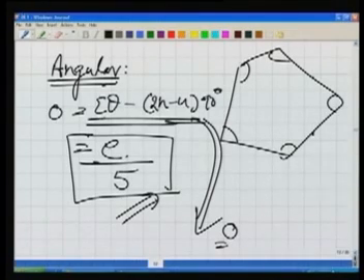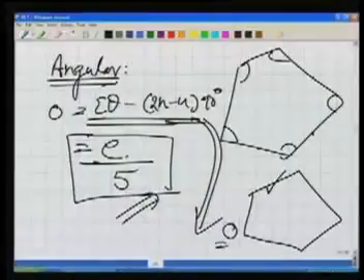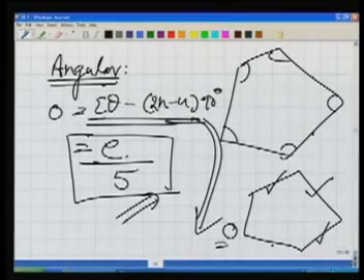If the angular corrections are applied and then we plot the traverse, still the traverse will not be closed. Why? Because we have not yet applied any correction for length. When we measured the length in the field, the length has got error. So no correction has been applied for the length so far. We have applied the corrections only for the internal angles. So our length will have the error.